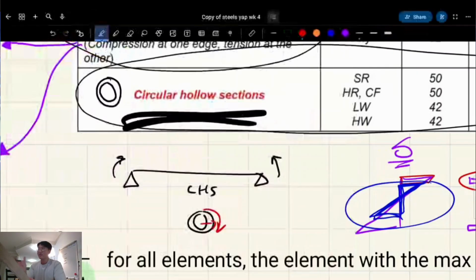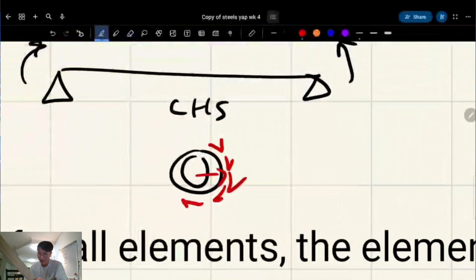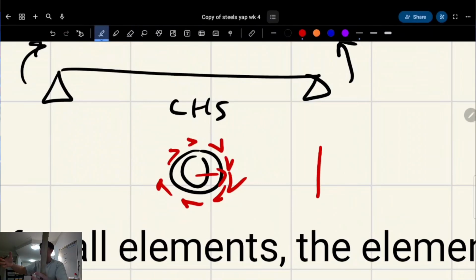Basically, do you know how the warping constant or twist is calculated, roughly? No. It's about how much meat there is. This looks really easy to twist. It's actually really hard. Imagine twisting a pipe. It's really hard, there's a lot of meat in the way. Compare that to a beam, a UB. Actually, no, just a rectangle, like a plate. A plate is incredibly easy to twist, right? If I twisted this, it's going to break instantly. Right, it's got the worst twist. And an I-beam's pretty similar to that, so that's actually got horrible torsional strength.